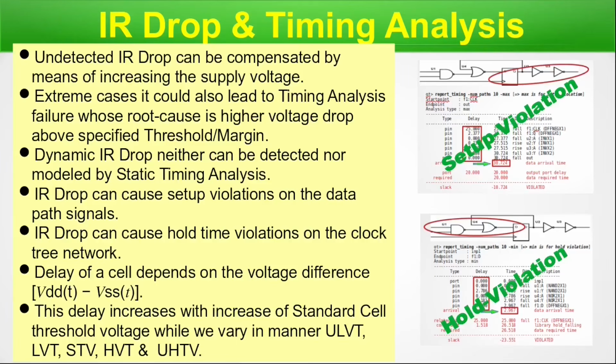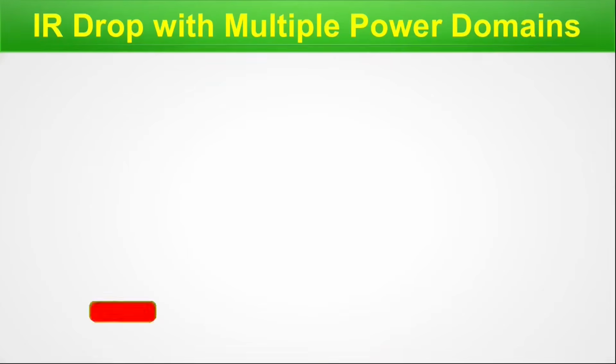So keeping all the points in mind, with the hit on the setup and hold violation as well as on the delay, altogether the timing analysis is affected by the IR drop happening in an actual chip. We are done with this particular slide. Let's move on to the next.